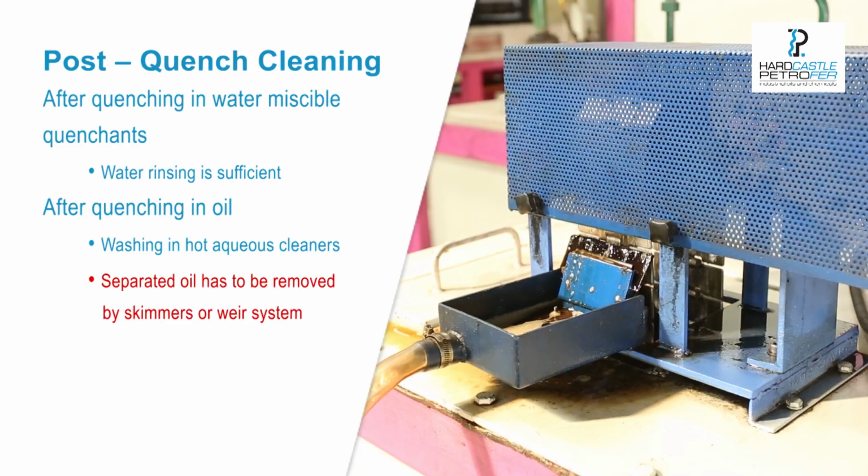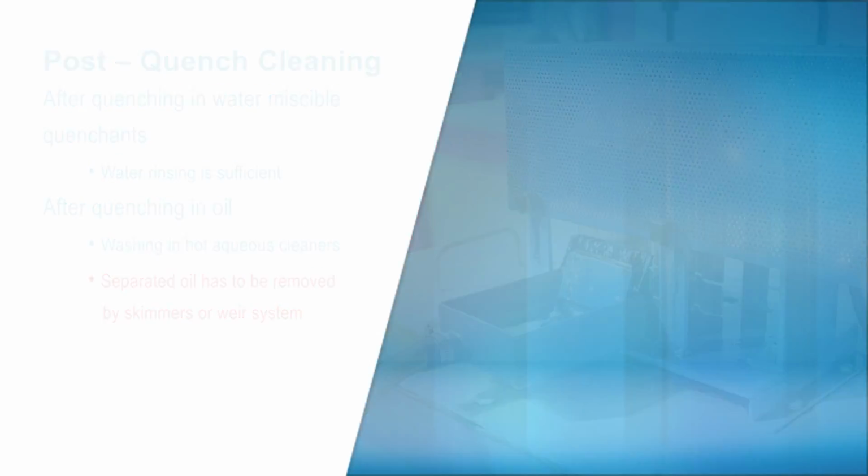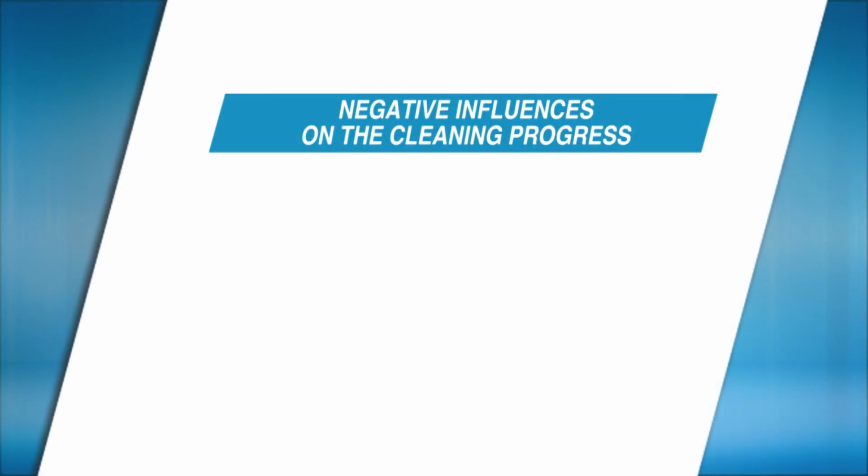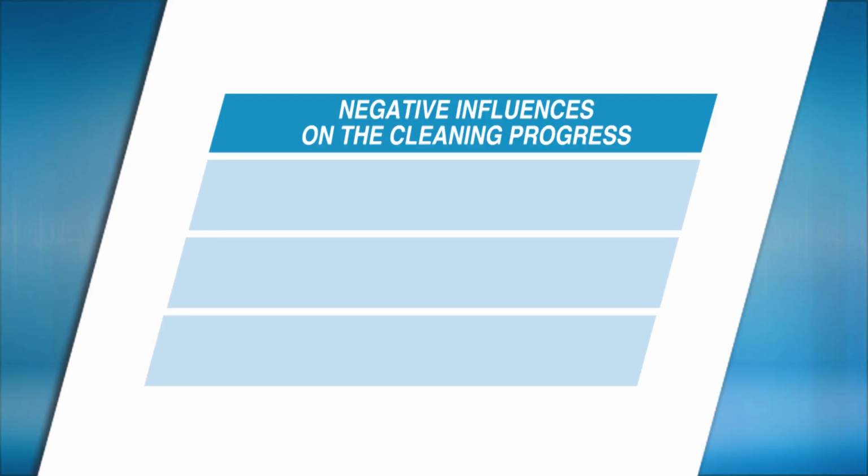Centrifuges also enable very good oil separation from the wash and can be used for both conventional and water-washable quenching oils. It is essential to exercise certain precautions to avoid negative influences in the cleaning process.